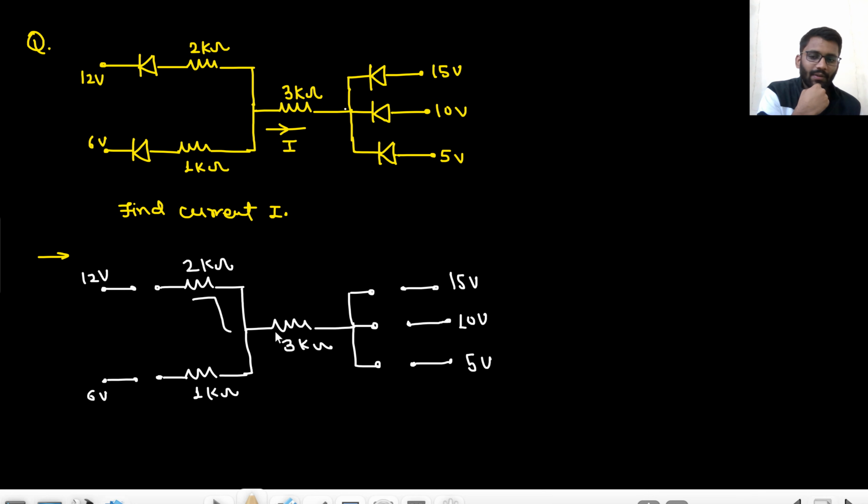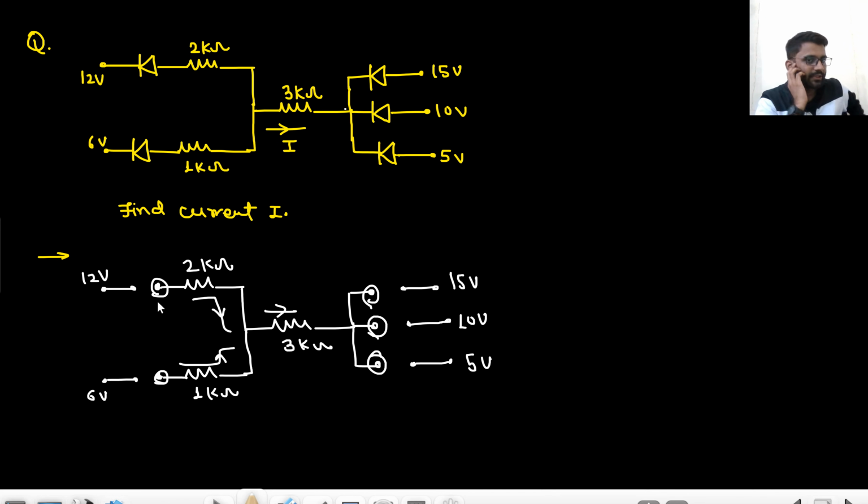Now what is the scene? Is there any current? All currents are 0, right? Do you know the potential of these points? Can you say it is 0? You can't say, because this is open-ended. None of the points is connected to ground. These are open-ended. You don't know what the potential is.